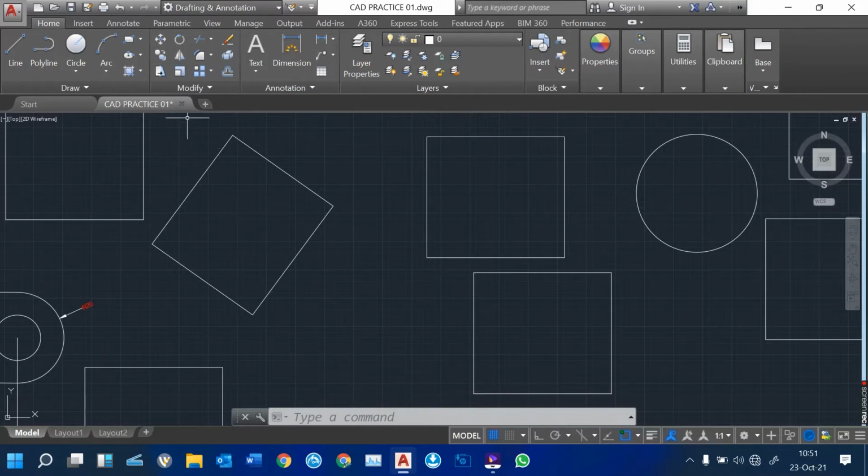So with all these tools, move, copy, and rotate, the next procedure, when you select an object, it asks you for the base point. Just pick any point near the object, and then you perform the function using the command that you've picked.